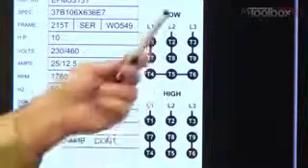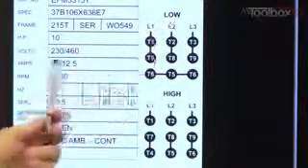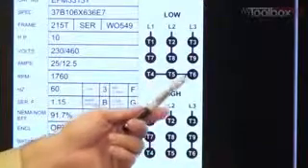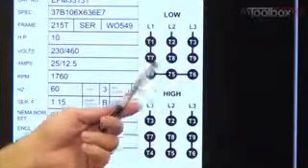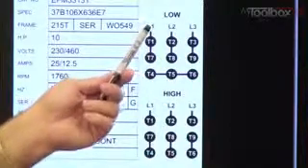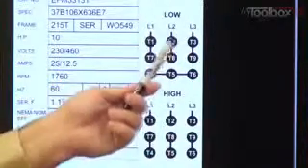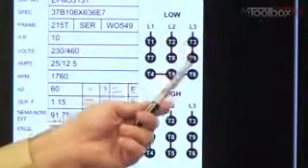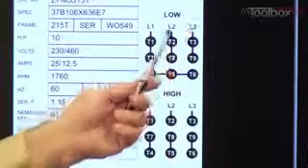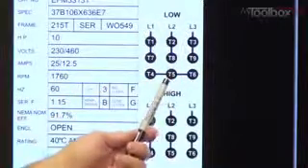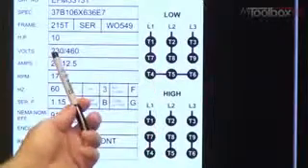If you want this motor to run at 230 volts, which is the low voltage, you hook T4, 5, and 6 together. Then you hook T1 and T7 together and hook that to L1. That's the phase lead. T2 and T8 together and take that to L2. 3 and 9 together and take that to L3. So this is your 3-phase incoming power. And that's how you would run this motor on 230.